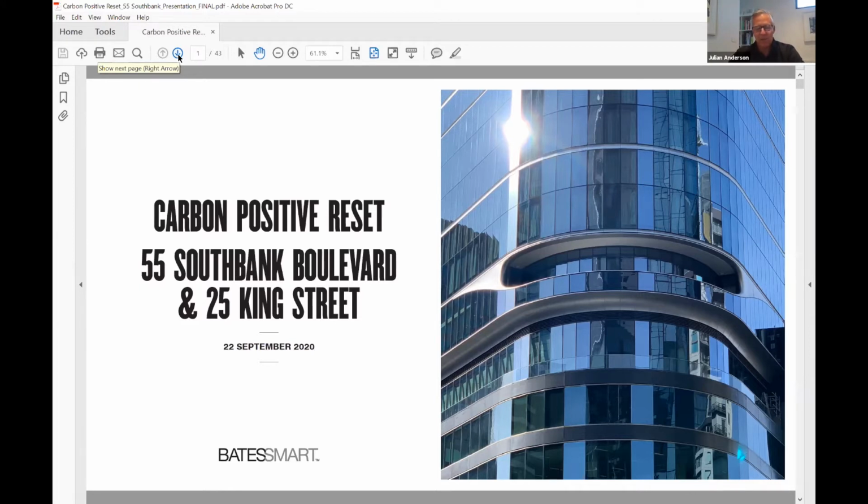One of the great benefits, as I'm sure you're aware, of cross-laminated timber is that it's time-saving on site due to large amounts of off-site manufacture, but this does mean that there is a need for greater time pre-construction for the coordination of the design, because all of the openings, including the service openings, are cut in the factory. And one of the great things about cross-laminated timber is that it is 20% the weight of concrete. Unfortunately, the most energy consuming aspect of cross-laminated timber often is its transportation, since so much of it is manufactured in Europe and Scandinavia. In the case of 55 South Bank Boulevard, our timber was sourced from KLH in Austria.